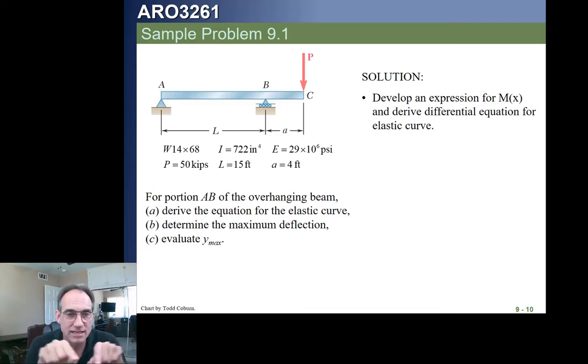Then we will go ahead, simplify our equation, and report either our W or Y of x. In this case, we want the deflection. We'd simplify our deflection equation. We can calculate what the maximum is. Remember, you find the maximum by taking the derivative of the function and finding out where it's 0. That gives you a local maximum or minimum.